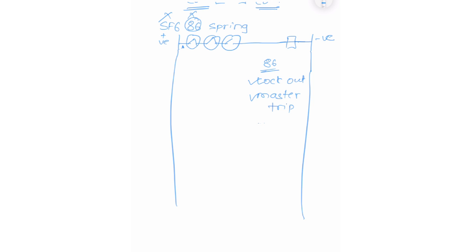So how is that achieved? There would be a lockout relay. Basically, this is also like a contact multiplier. However, once the relay is picked up, it will hold its condition in most cases. It comes with different types of reset. This can be a manual reset in which you need to push the button. It can be an auto reset, in which case it resets on its own once the command is dropped. Or there can also be an electrical manual reset.